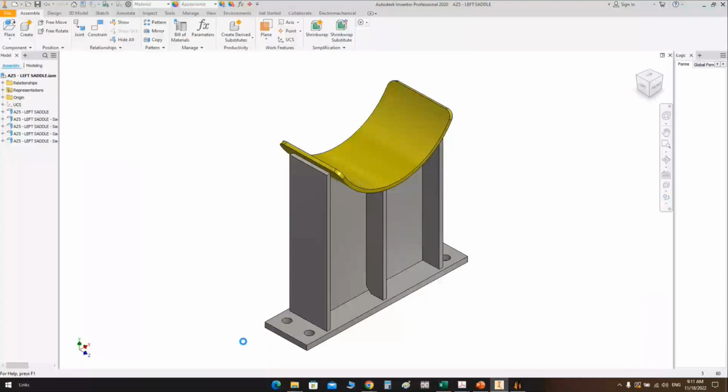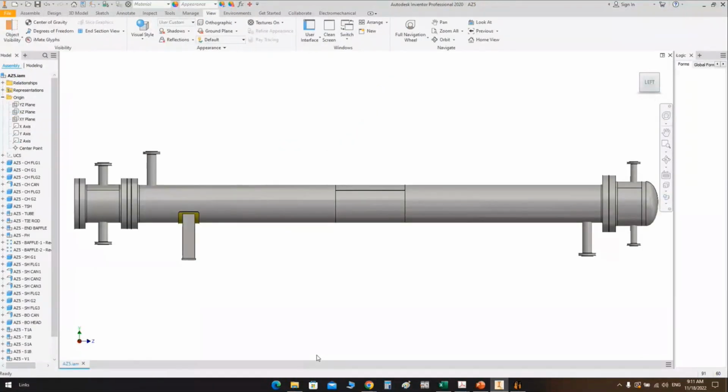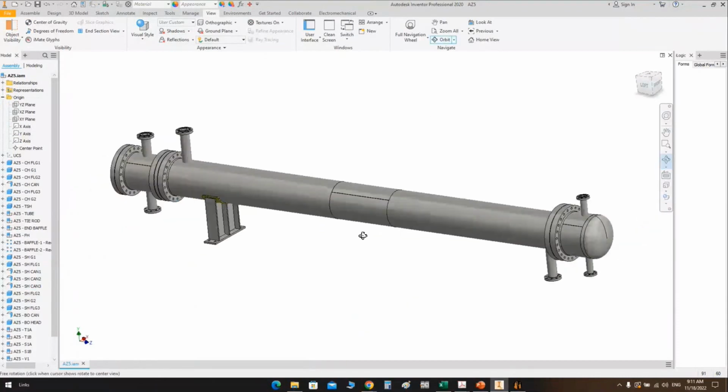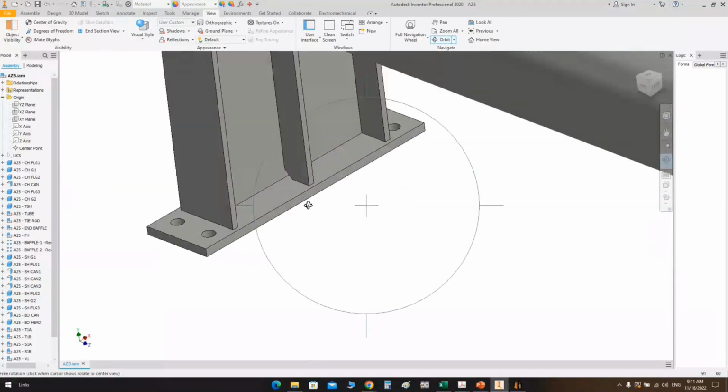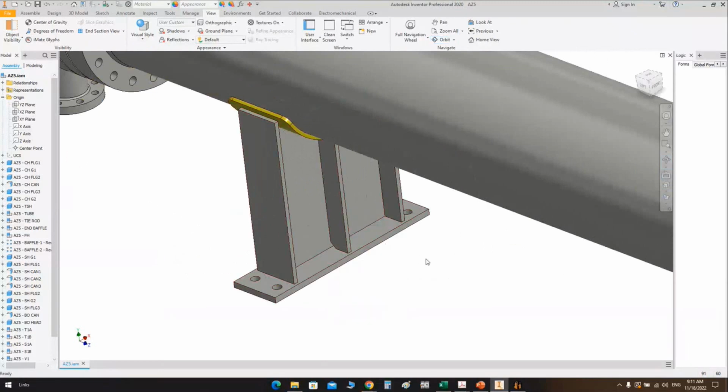So after creating the 3D model, you can make some customization, like if you would like to decrease the base plate length and move the holes to the inside. So the 3D model will guide you if you would like to make a modification on your mechanical calculation. After reflecting it on the 3D model, you can see that for fabrication reasons or something like that, you will need to make a modification again in your mechanical calculations to suit the fabrication requirement.